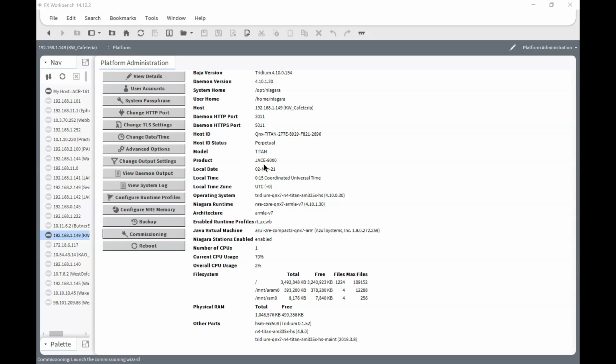If you want to go ahead and open up this other port, like if you connect this JACE to the server at this property, and you already know the IP address, you can go ahead and enable this and put all the IP address information in there. Or you can do it on port 1 and then change your port 2 to default.